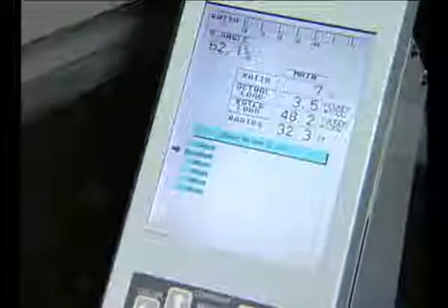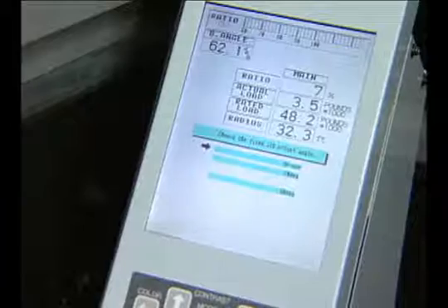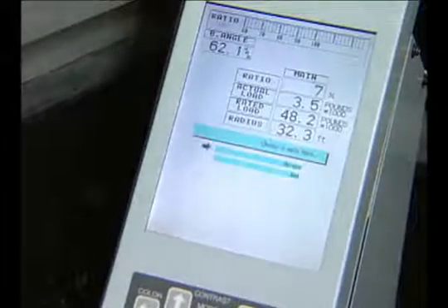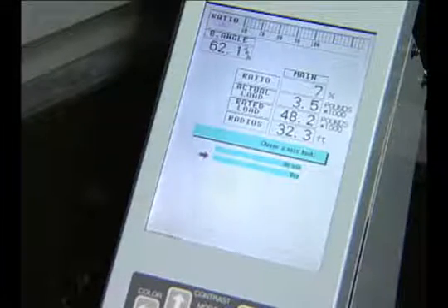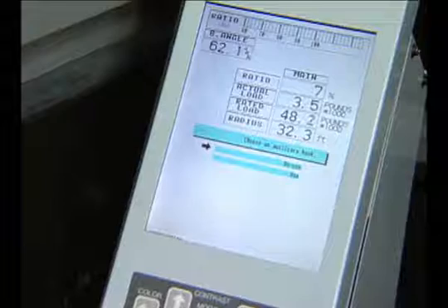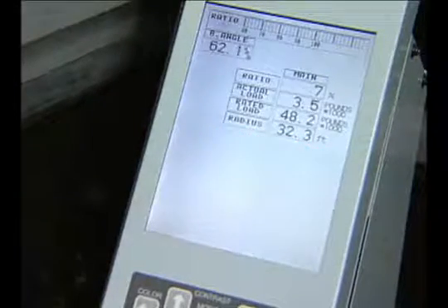Next, choose the kind of jib. We will select Auxiliary Sheave and push Set. Then choose Jib Offset Angle. We will select Unused. The next screen will show Choose Main Hook. We will select Use. The next screen will show Choose Auxiliary Hook. We will select Use and then push Set.